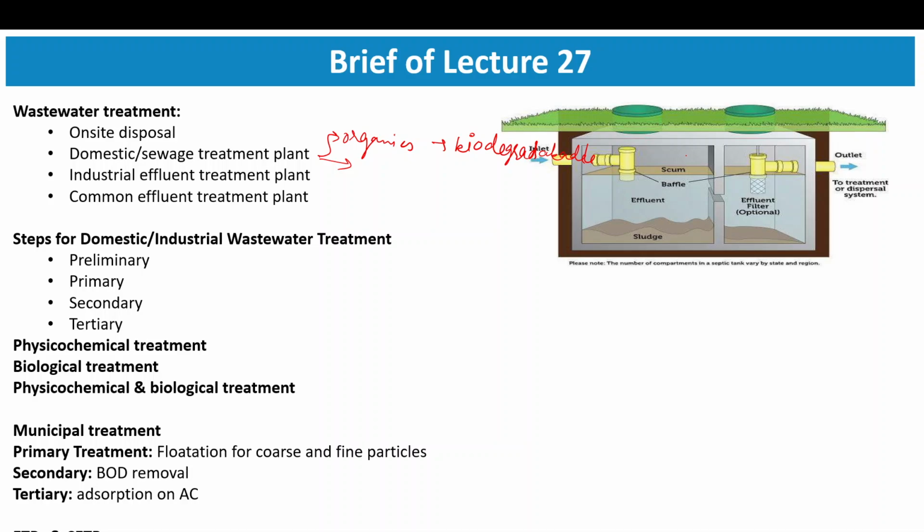Such pesticides and insecticides are difficult to treat, but comparatively they are less, and the BOD is much higher. Majorly the organics are biodegradable, so for biodegradable ones we can use some microorganism treatment for their degradation.